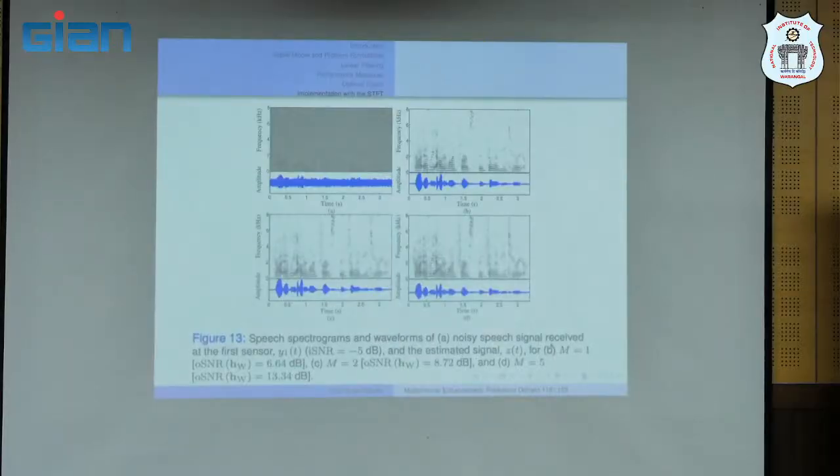So you can take the MATLAB code for these figures, for this example. You can play with it. Multi-channel speech enhancement with multiple sensors. It's a very nice example. If you have time, go through, play with it, compare to the single channel. Okay? But there is not much to talk about it because it's very simple. Instead of the Fourier transform, we work in the STFT domain, and we find for each frequency bin a filter.